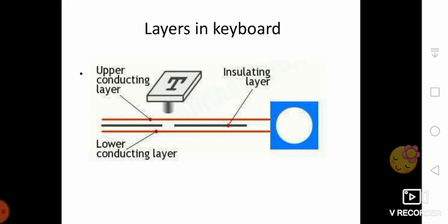In all the keyboards, each circuit is broken at a point below each key. When a key is pressed, it presses a switch, completing the circuit and allowing a tiny amount of current to flow through it. Then the mechanical action of the switch causes some vibration called bounce, which the processor filters out. If the key is pressed and held continuously, the processor recognizes it as the equivalent of pressing a key repeatedly.